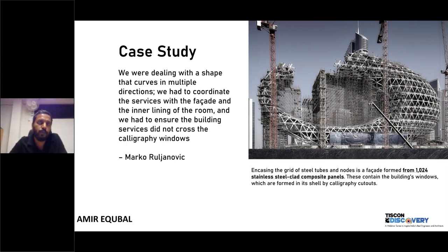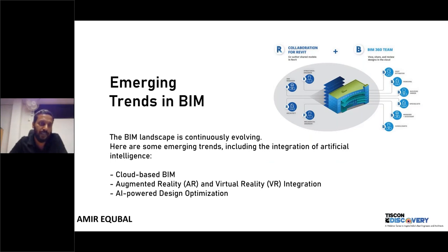So one is that earlier, the challenge was that you don't have infrastructure. You have a lot of excuses and reluctance in adopting BIM, that you don't have a big infrastructure, you don't have the computers that can run these big softwares and all of those things. But to solve that, there's the concept of cloud-based BIM. So you don't have to have your very high configuration computer system that can run the model, but you can always have a subscription on the cloud on a monthly basis or pay as you go, and you can store your model there, and from your computer you can operate it over high-speed internet.